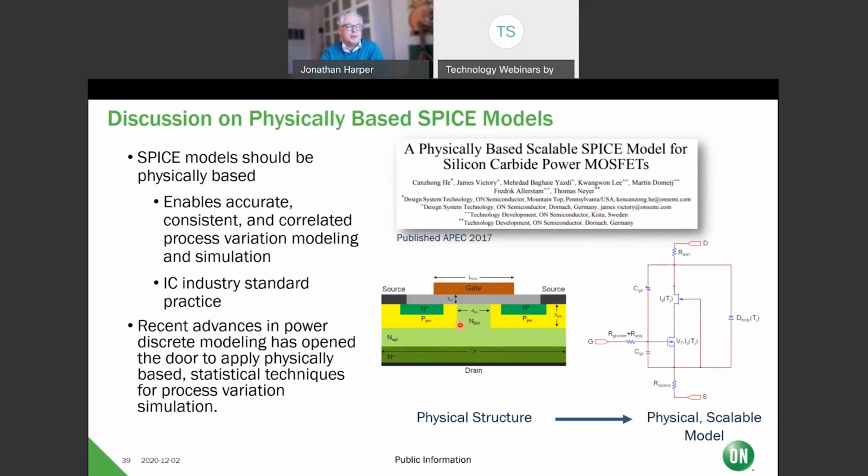That's also important, especially in the automotive world, where you want to say, okay, you say your gate oxide is this. What happens if it varies a lot? What about your process parameters? We do that indirectly from the models. We take the worst case parts and then we feed them back in and make these models so you can actually determine the reliability very easily.